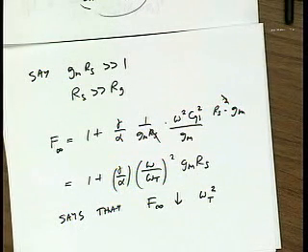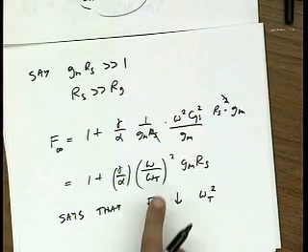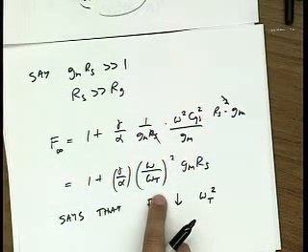In the long channel regime, it got better like 1 over L squared. Even in the short channel velocity saturated regime, it gets better by 1 over L. So today you can go out and buy yourself a transistor with an FT of over 100 gigahertz. So if you're operating at 1 gigahertz, you can see that this term is going to be quite small.